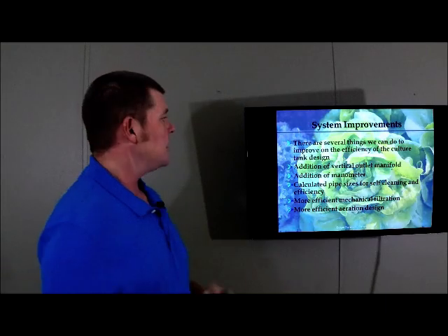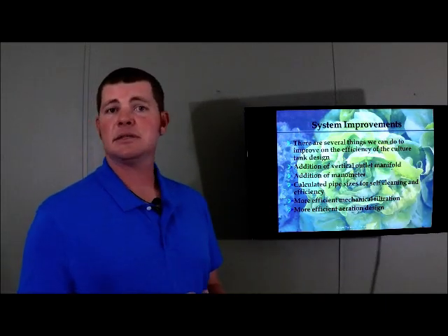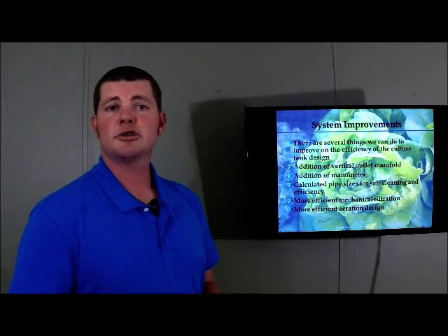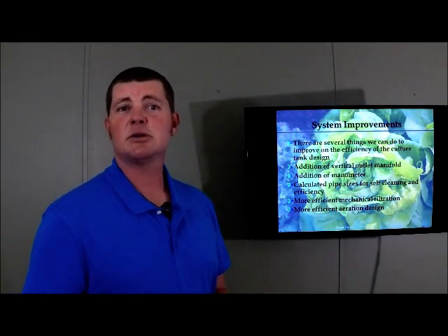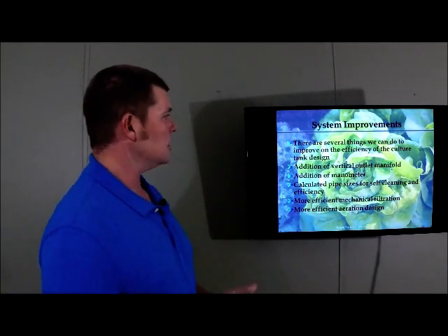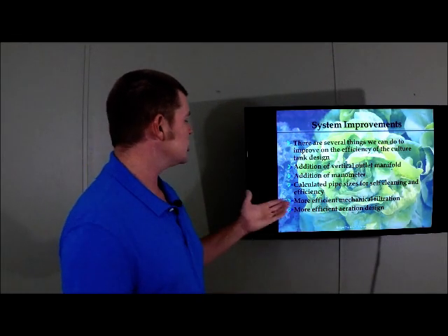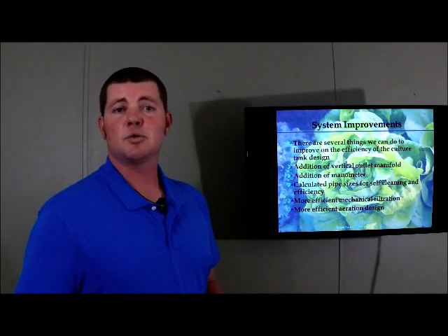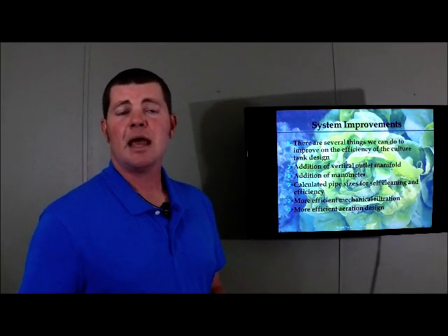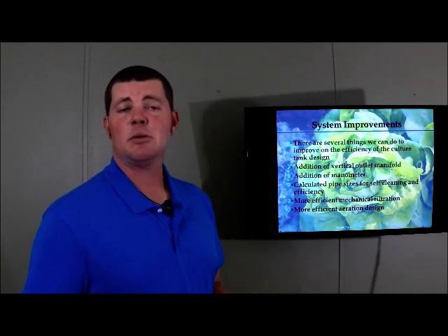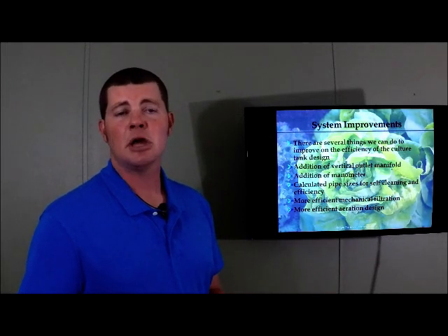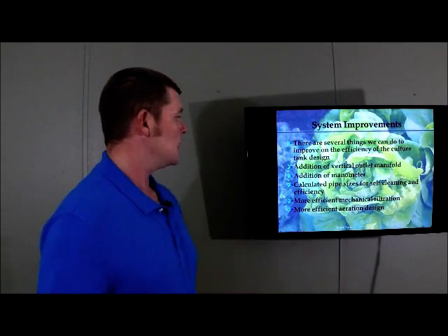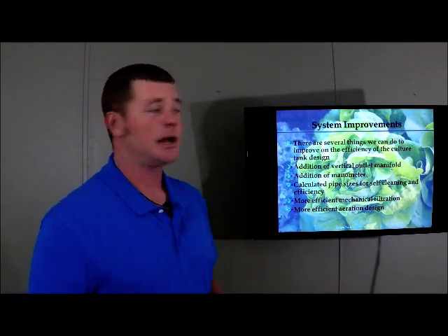of the cone. They also stock some tilapia in this tank to help keep solids moving down that cone closer to the drain, but sometimes they stir up those solids. Well, we'll talk a little bit about this later, but we can actually shrink that filter probably by 3 to 4 times, which would be a lot less expensive and a lot easier to maintain. We'll actually pull out more solids with a filter that's 1/3 to 1/4 the size of these filters. So that's somewhere we can improve this design.